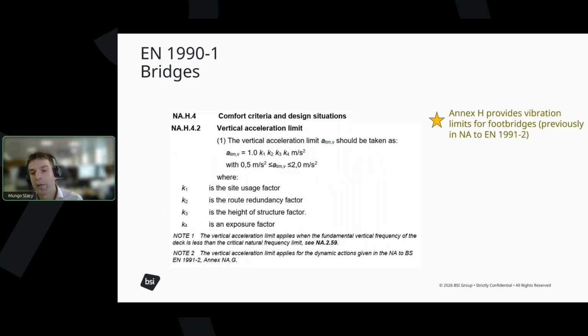We also have some new content on serviceability limit states for accelerations and vibrations of footbridges. The UK content will be based on the approach given in the National Annex to 1991 Part 2 for traffic actions.